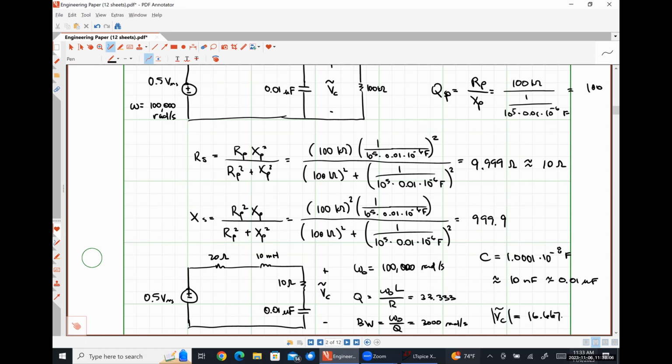We'll talk about a little something about that here in a moment when we're talking about filters and all that kind of jazz. I think that would probably be the easiest way. Another alternative way would be to just run a simulation, because this is just a simple RLC circuit, so it should behave pretty effectively. If you were able to accurately measure your inductance and your capacitance using an RLC bridge or something like that, you can get a pretty accurate model of what's going on.